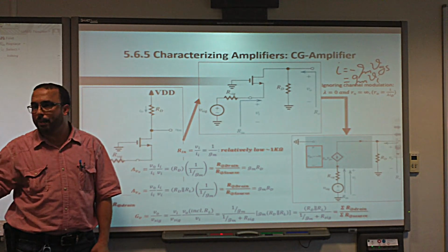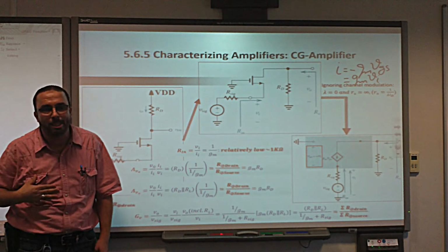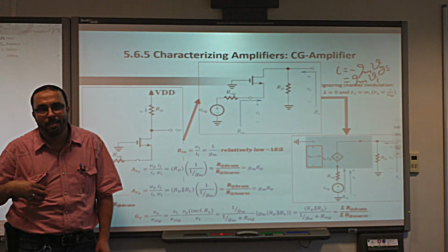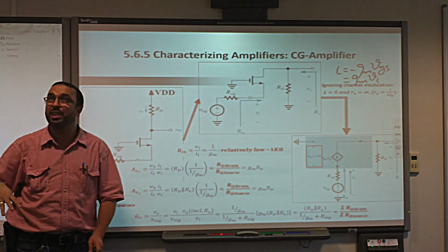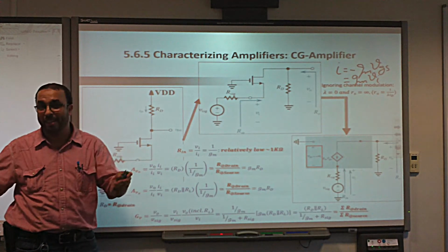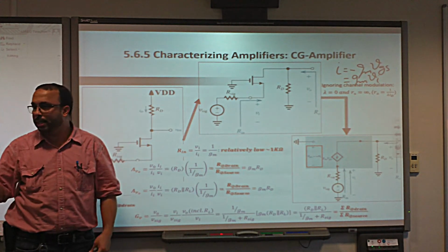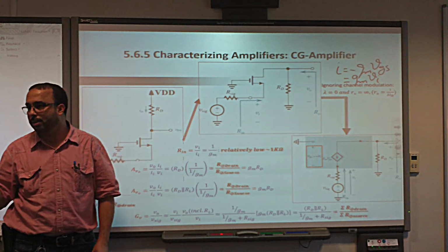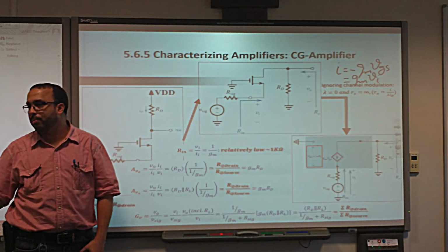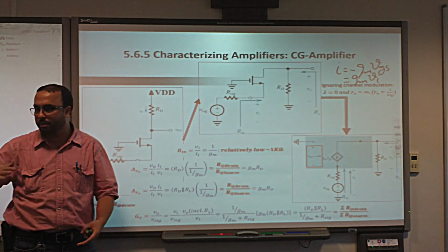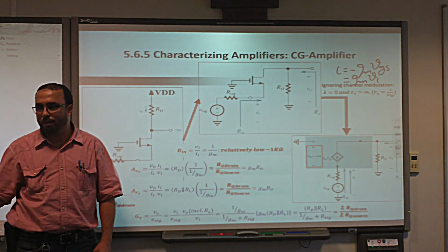Remember gm in the last couple of classes? When we compare BJT to MOSFET, gm is equal to roughly how much? Between 0.35 and 3.5, remember? When you have W over L equal to 100 and we use the gm equation. Revision would be helpful as well. So typically it is in the range of milliamp per volt, between 0.3 and 3. Let's give it 1, because 3.5 happens to be at W over L equal to 100. So let's give it 1 milliamp over volt, gm.